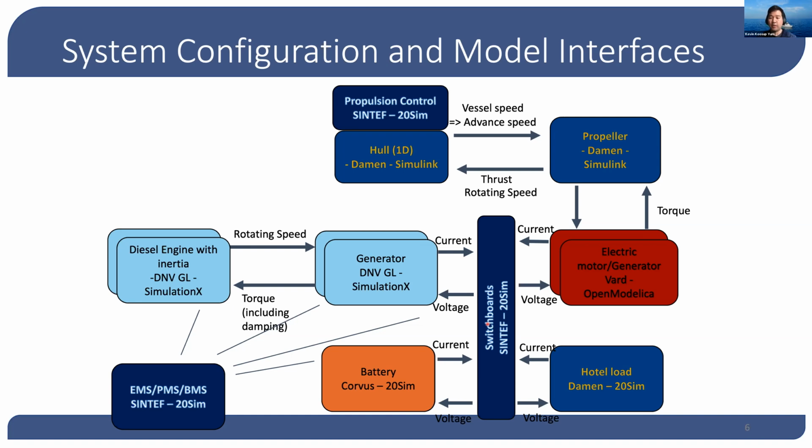The system simulation typically runs 30-40 times faster than real time, which is ideal for early design trials. And this system model can be further elaborated in the later design stage while keeping its structure to serve other needs such as design verification, hardware-in-the-loop testing, and virtual commissioning.